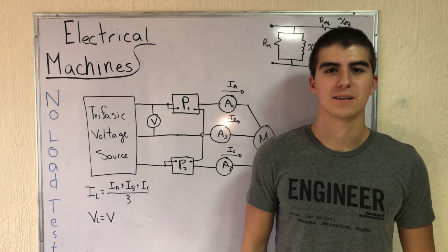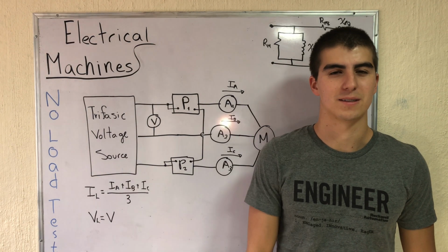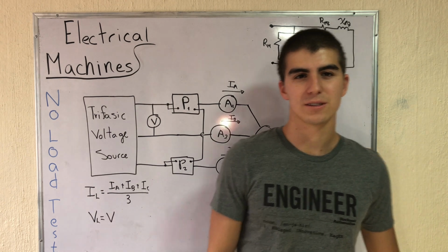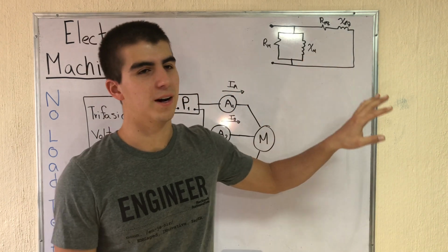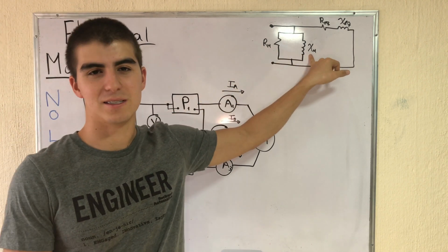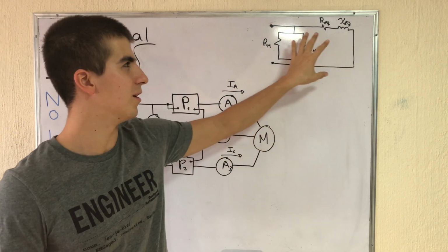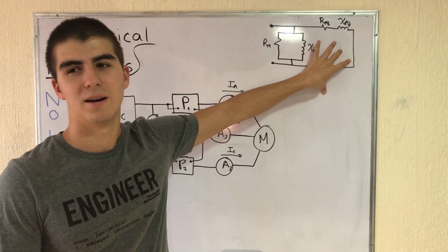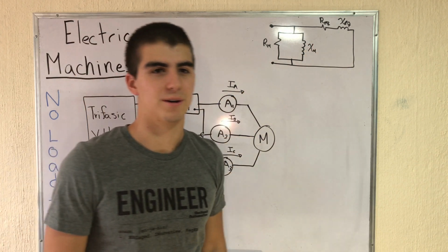The first test is the no-load test. This test allows us to find the values of the magnetizing resistance and the magnetizing inductance, remembering that this is the approximate representation of a motor.